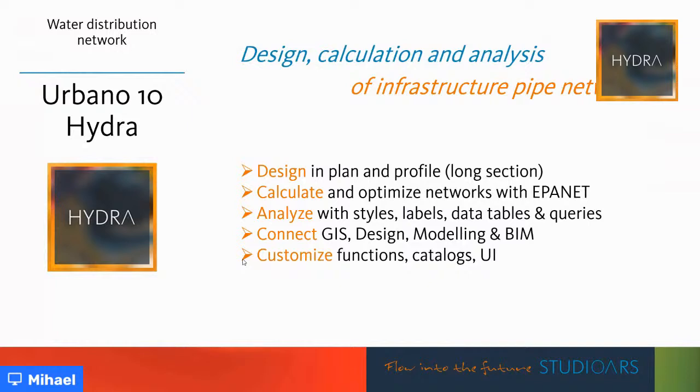So if we break it down to the specific functions, you can use Urbano Hydra to design plans and profiles, to calculate and optimize networks with the EPANET calculation engine, which is built into the software. You can, of course, analyze your networks and hydraulic calculation results.